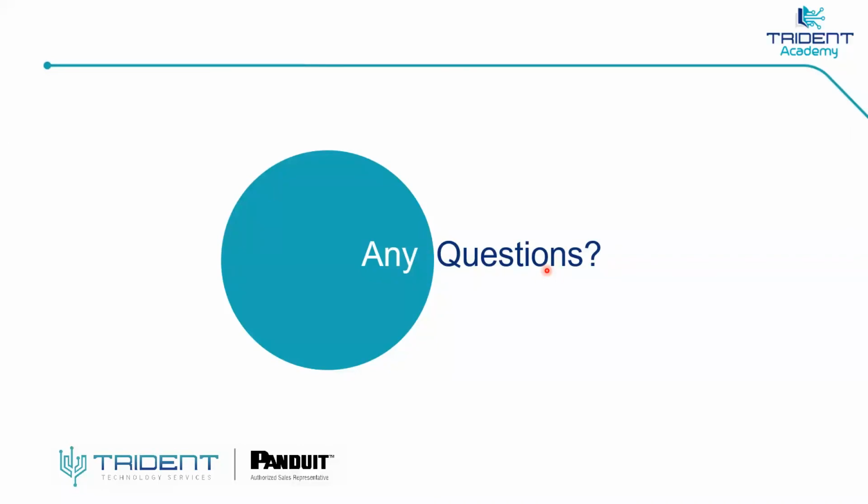Mr. RGL Panker is asking, do Panduit panels come with earthing and bonding strips for the various categories? He also mentioned that he would love to apply to Panduit. It's a dream of his to become an RCDD. He said the technology at Panduit is brilliant. Okay, thank you very much. When it comes to the earthing bond, no, it's not coming with the panel. The panel comes as a metal module, and you need an earthing cable to connect to a grounding bus bar or grounding strip inside the cabinet. And thanks for your words.